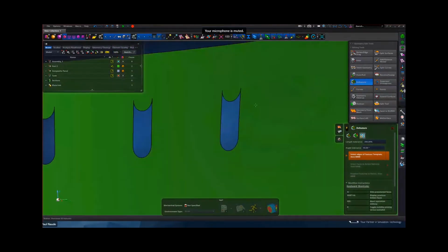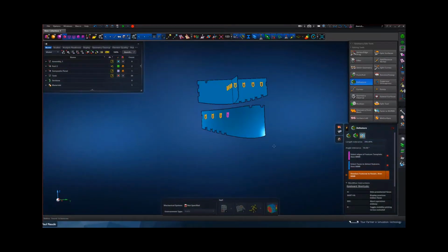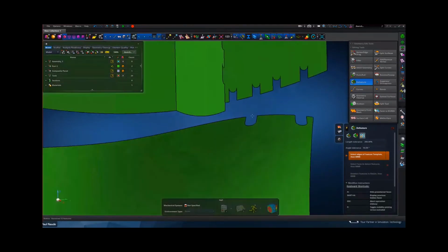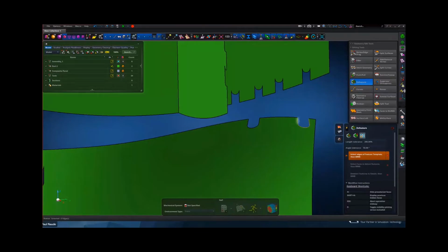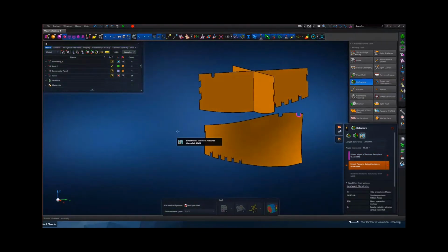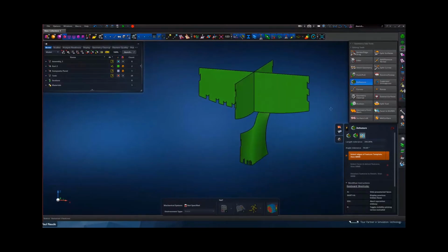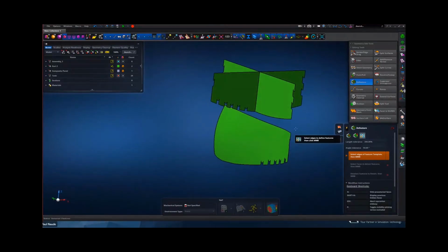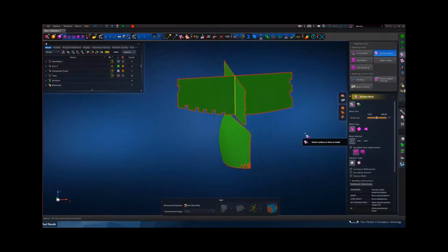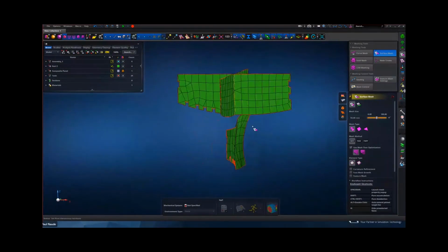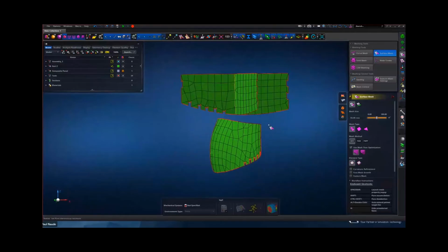I can go ahead and remove those by redefining them through just clicking the selection of edges that defines that new shape. And now you see it has found them, and I can remove them. Okay, so here's a few of these that didn't go along in the previous group. Let's see, it finds them, middle mouse click, and they're gone. And you can continue doing this for all these other parts, but I hope you get the idea. And obviously this now severely improves the mesh on these bodies, as you can see where those features have been removed.